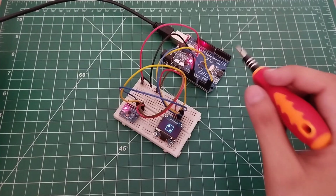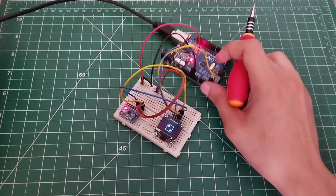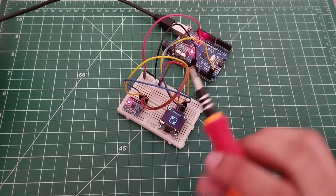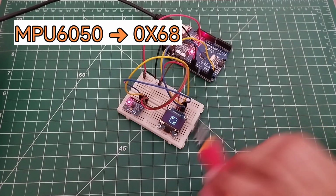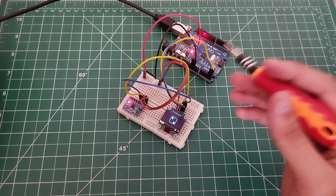Now the question may arise that if both of them are connected on the same bus on the Arduino, then there must be a conflict between them. But the point here is that multiple I2C devices connected on the same bus doesn't mean there must be a conflict, because all the I2C devices have different addresses. Like the MPU6050 has a default address of 0x68. Similarly, the OLED display has an address of 0x3C in my case, and some OLED displays also have the address 0x3D.